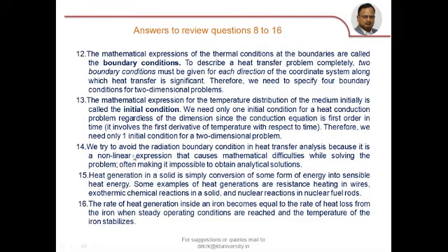Next, coming to the 14th question, we avoid the radiation boundary conditions. For example, take a plate. The heat conducted through the plate and reaching the top surface enters into the environment by means of radiation. Imagine. So the condition is conduction heat transfer passing through the plate is equal to radiation heat transfer into the environment.